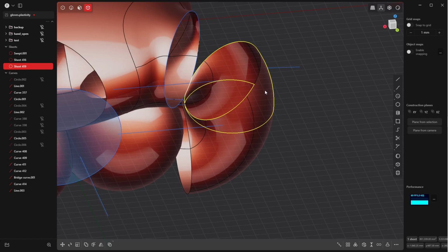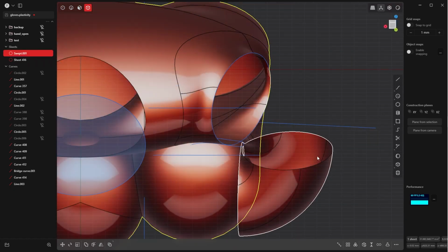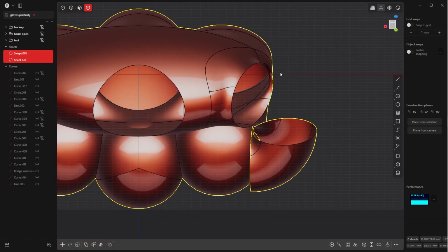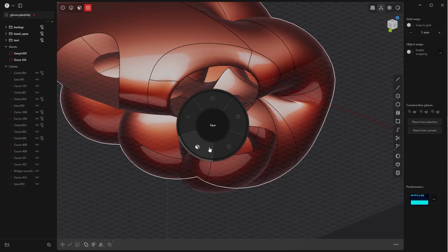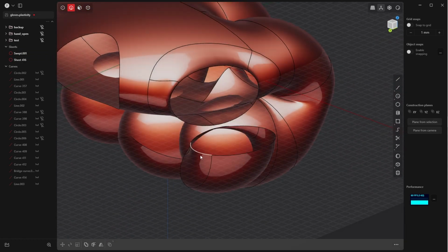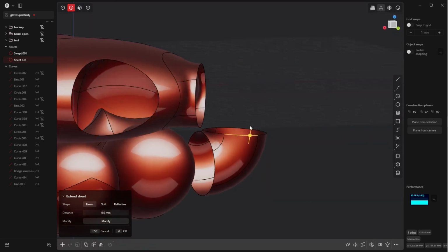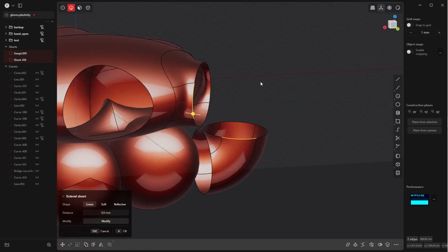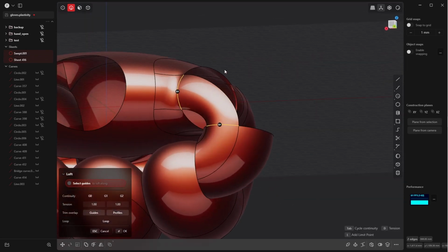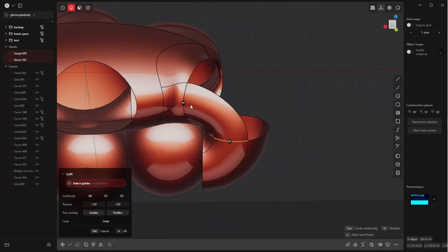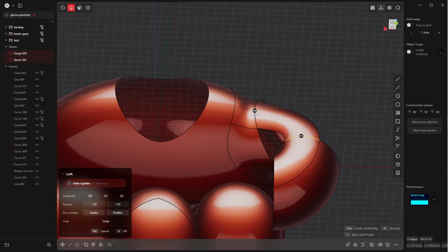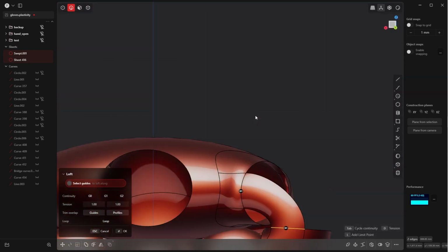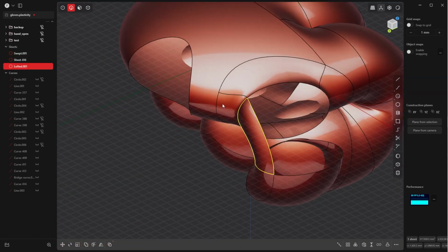Let's delete it. Select both parts, the thumb and the hand. Shift H. Let's try to loft these guys by going to edge mode. Select this one and then this one. Let's loft them. Yeah, this looks okay. Even try. No, this looks too wobbly. No, that's not what we want. G1 is completely fine. Press OK.